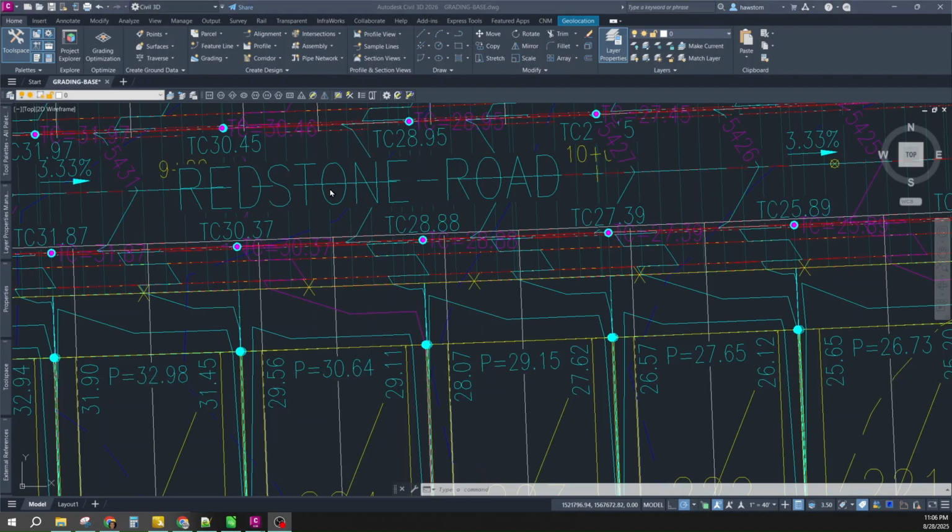Now, what's it doing? Well, this street is draining from left to right, and we want every pad to be high enough that its side yard can drain out the high side, but we don't want it so high that, in the case in this subdivision, that the driveway is on the low side, the driveway is too steep. So we gave this pad elevator some rules.